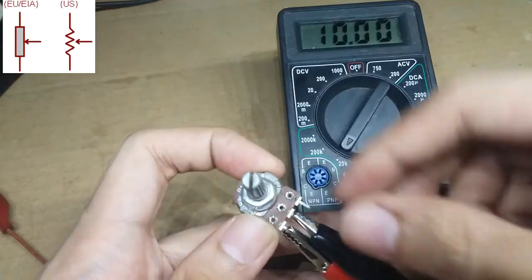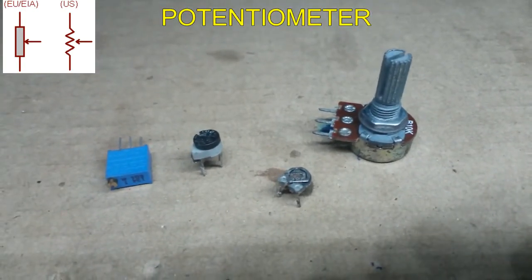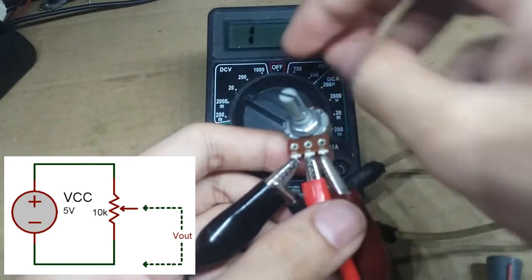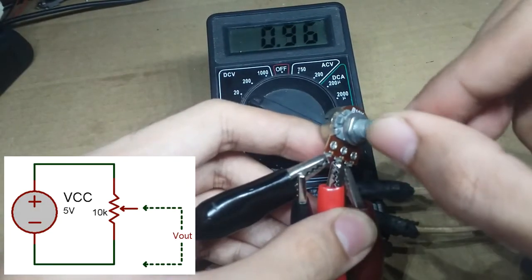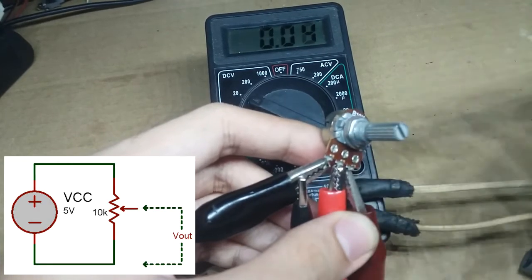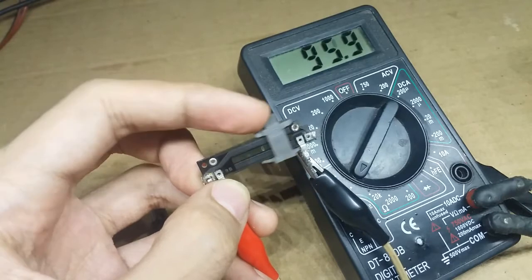There's also a resistor that you can vary the resistance of. They are called variable resistors, or we can call them potentiometers. Commonly, they have 3 terminals. You can connect these terminals to a supply. Now it functions like a voltage divider, but its output will change when you turn the knob. So you can see potentiometers on sound amplifiers to adjust the volume. There's also another variant. Instead of turning, you will slide it.